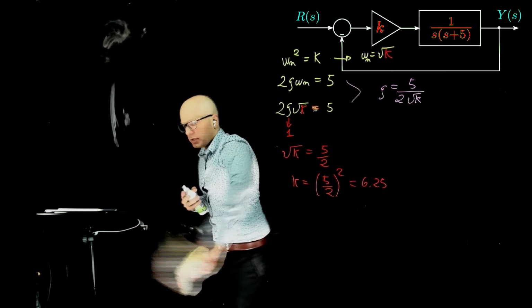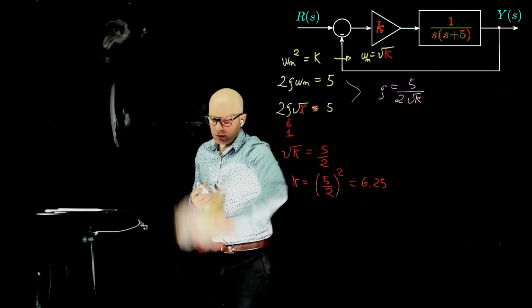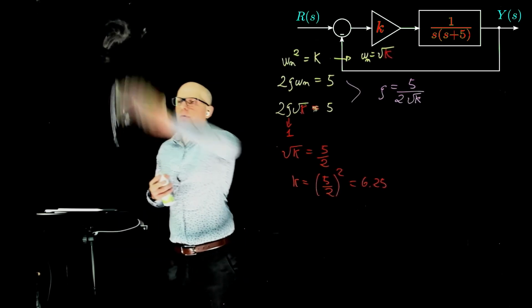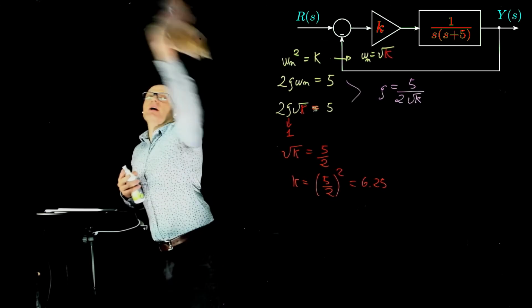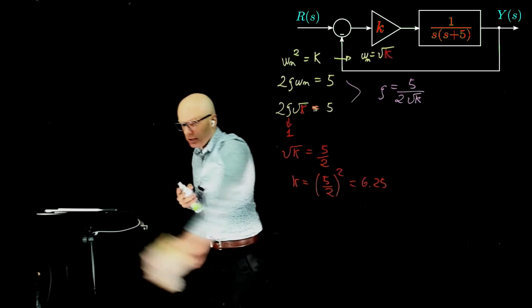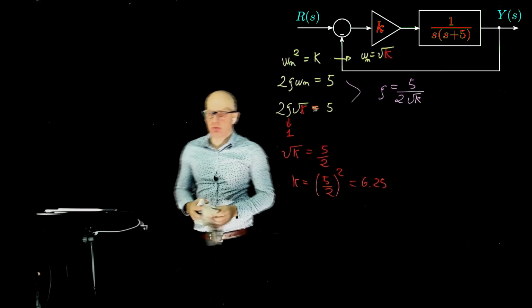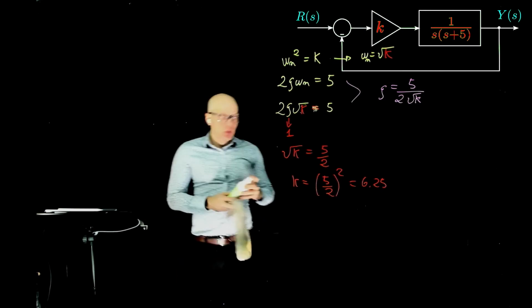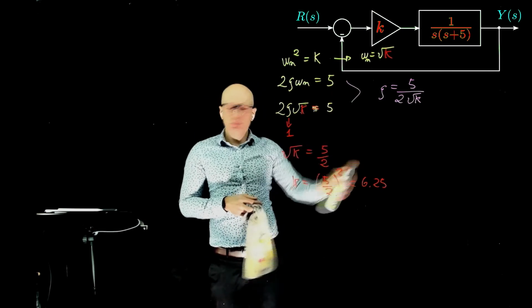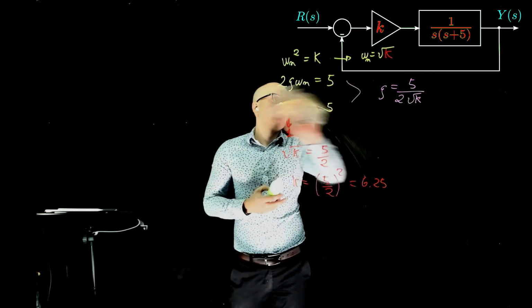Right, yes. We know that the higher k, the lower the damping ratio, right? So that will give us the maximum value of k before the system becomes underdamped and an oscillation starts to show. Okay, good to know. Just like do some limit things. Yeah.